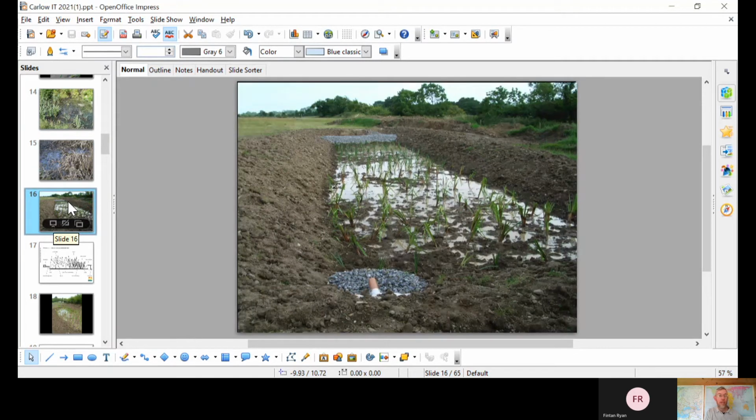So if we look at how do we engineer a natural landscape to form a constructed wetland, taking those elements into account. Here's a system in North County Dublin. So it's fully plastic lined. There's a plastic liner underneath that. There's about a foot of soil put back in on the plastic liner. The bed of the soil is made level, planted up with various wetland plants. There's 2 inlet pipes, one here and one just out of the frame, and the liquid moves across the surface of the water and gathers in an outlet pipe at the far end and off on into a percolation area.